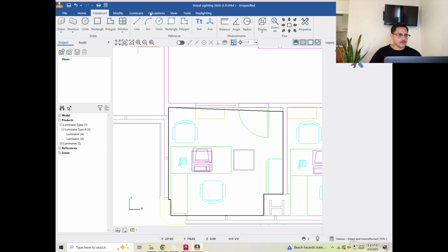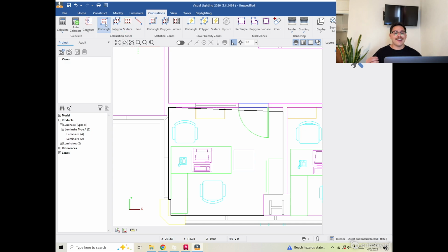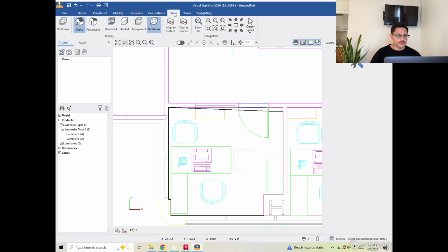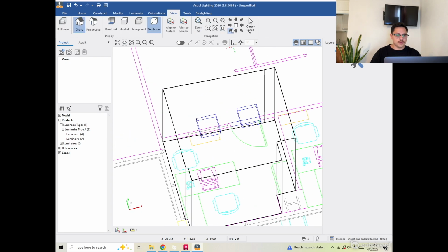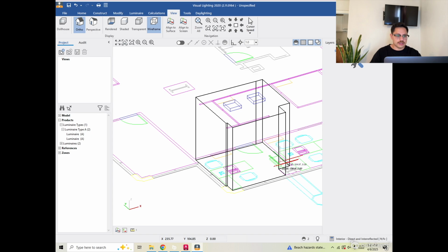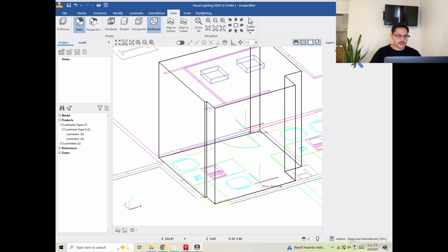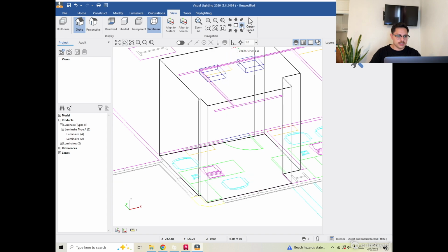Okay. Now we're gonna make our calculation zone. This is basically how much light is within that room with these 2 light fixtures within that room. And just so you can see, we're gonna just move around. How do you move the view? So with the view, you can move around, and that's just kind of how the room's laid out. You see, it's an entire room, the light fixtures on the top. Since they're recessed, they're at the very top.